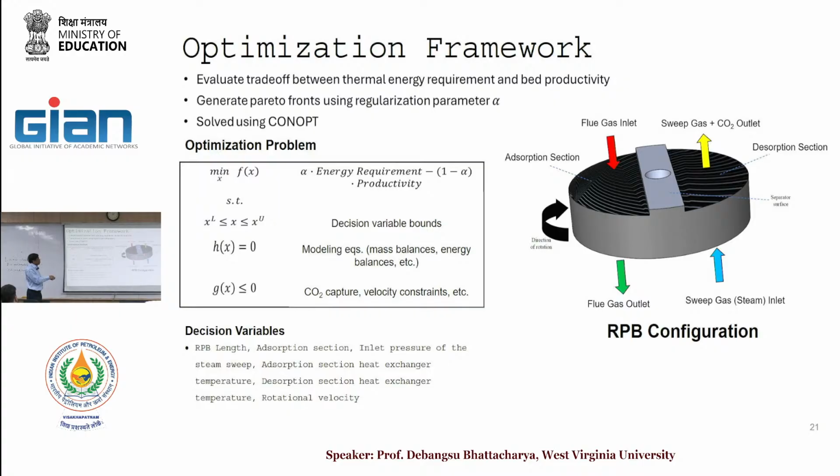Then it comes to the desorption. Again, we are just showing it for the cartoon. We are showing only adsorption and desorption, but you could have other steps. But the moment it comes here, it comes in contact with steam, and then desorption actually starts. So as it rotates, it desorbs, and then it enters this adsorption section.